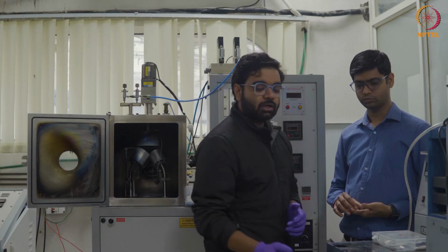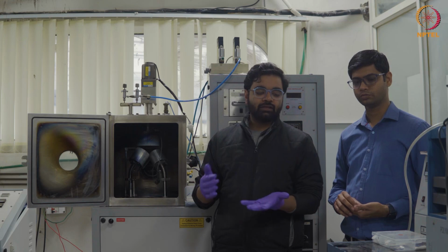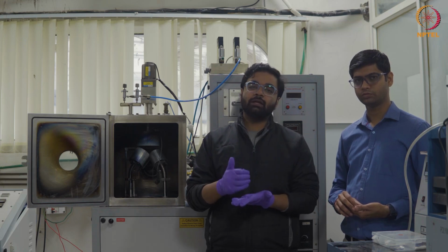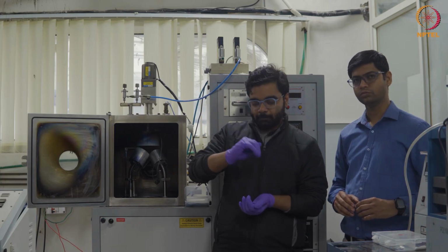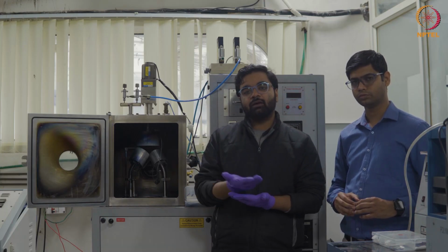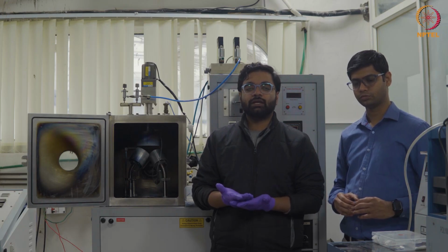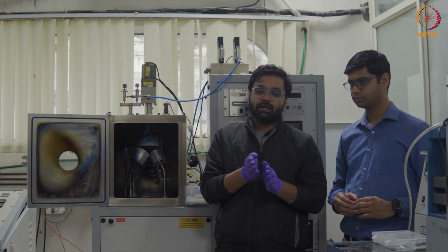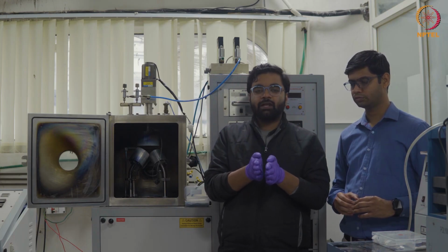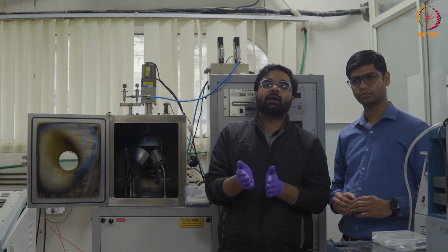Then, if we talk about the fine feature size, the controllability of the system is also very important. In our case, we are using laser printing, so because the laser hits the surface, the material ejects out, and since it moves on an XYZ stage, which is an automatic translation stage, once the material transfers, the gap that we can get between two lines can be in some microns, that is 5 to 10 microns.